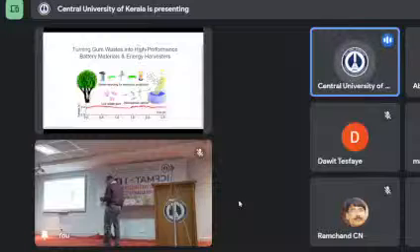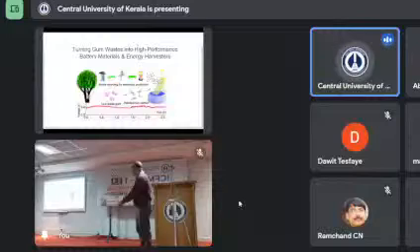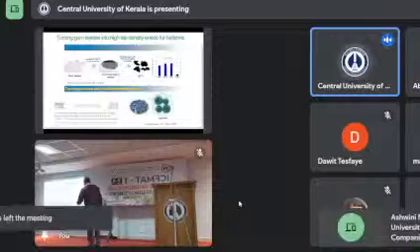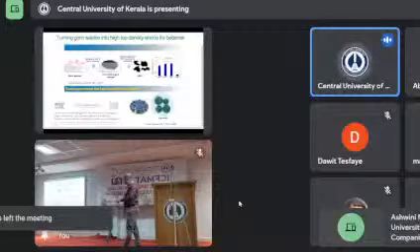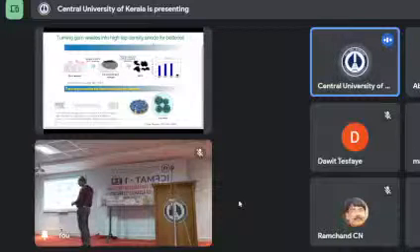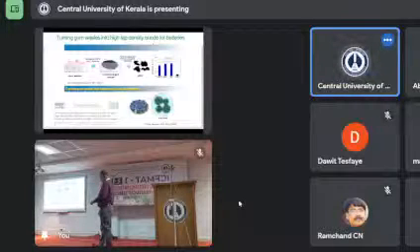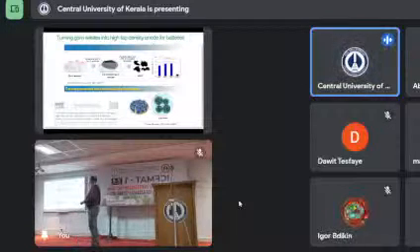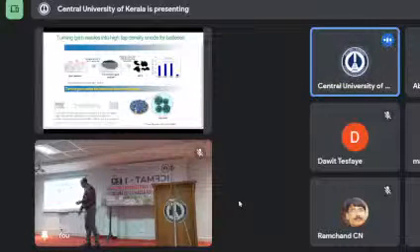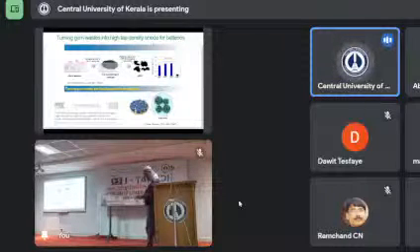Now I want to show how we can use this gum waste to make high performance battery materials and energy harvesters. This is the process. When you use a gum waste material, we pyrolyze it at 800 degrees Celsius under nitrogen, and you can make a carbonized gum waste. With some treatment with KOH, you can get micro or nano carbon material that can be used for energy. You can use this material for electrode applications.